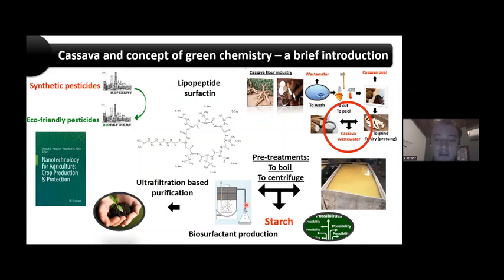It's a quite different biotechnological process because there's a lot of foam produced. We can recover this foam from the top of the bioreactor, and after that, we can run some purification process. The most prominent purification process is ultrafiltration, which is a membrane-based step.